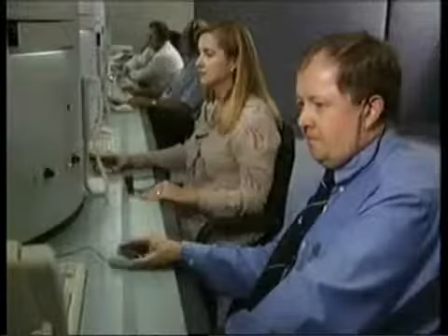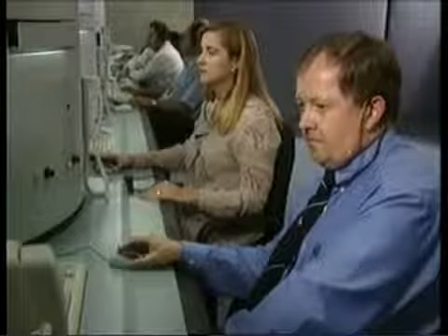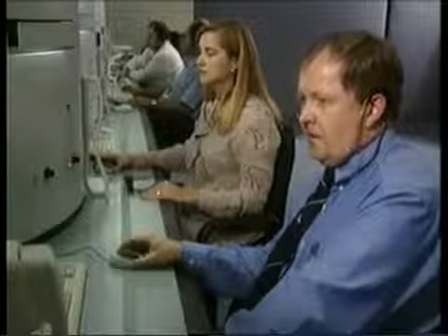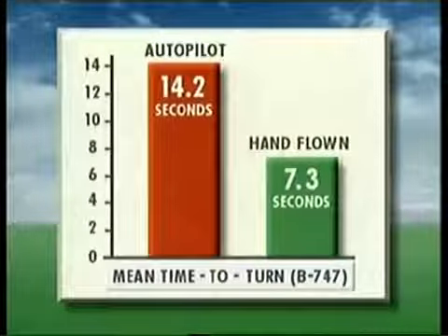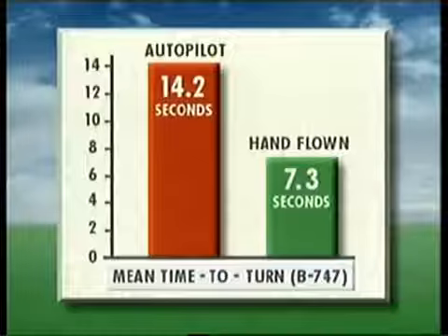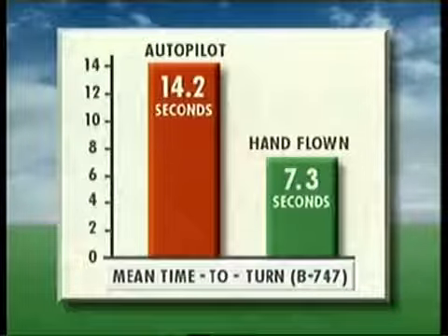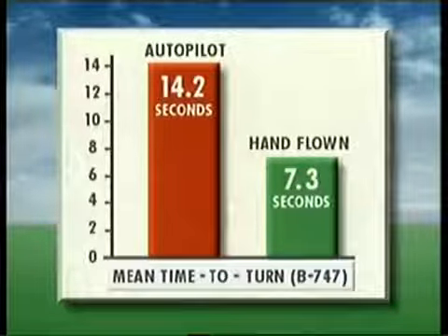First, why do we have the descending breakout? Extensive simulation has shown that there are times when the controller has only one tool left, hence the inclusion of the descending breakout. Second, why hand fly the breakout? Again, simulation has shown that hand flying is the fastest way to start the aircraft turning, and that turn is the most important element of flying a successful breakout. Let's again look at the breakout procedure.